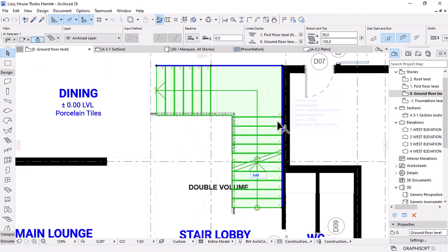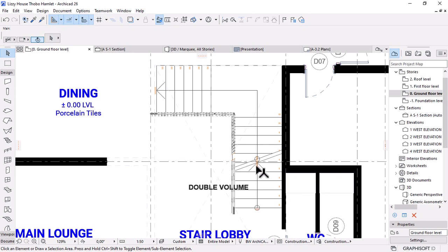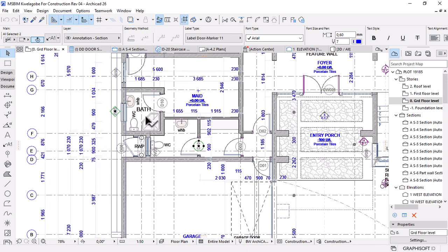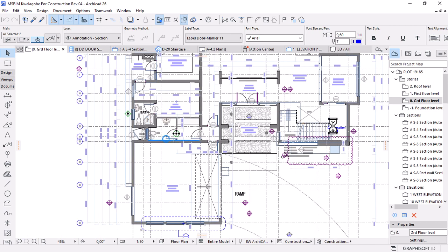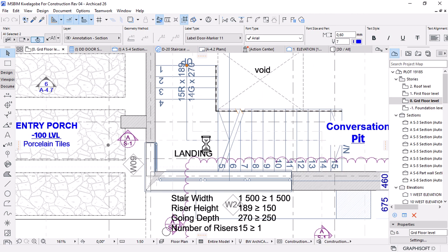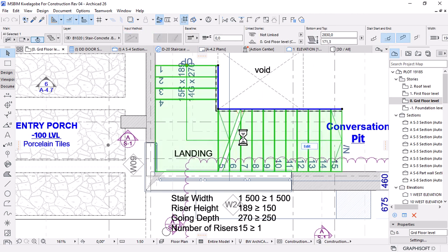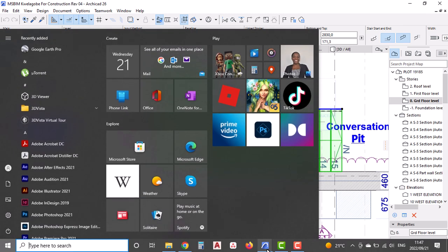The staircase, you can see the numbering is not visible enough. It has to be relatively equal to the height of this text. I mean the numbering. And if you look at it, the representation is also wrong. Let's go back to this previous project and look at its staircase. We can maybe copy it like that and then paste it here.